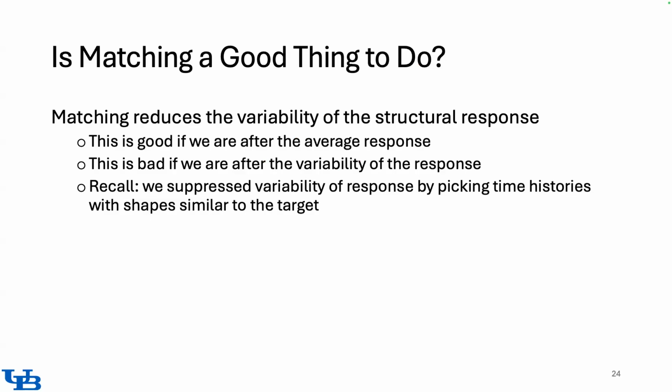So this type of analysis is something that you may want to do if what you are really after is characterizing the mean structural response of your structure, because you suppressed all of your variability. But if your final goal is also characterizing the variability of your structure, then maybe simply scaling the ground motion is a more appropriate analysis.